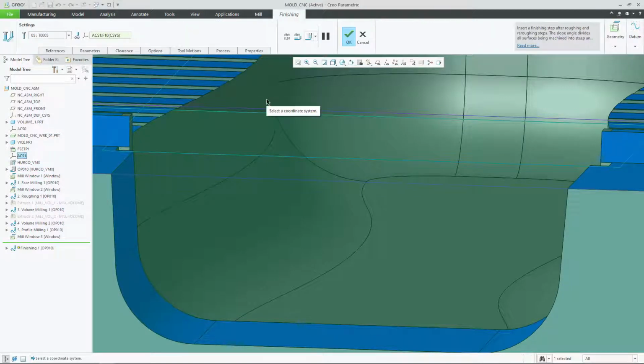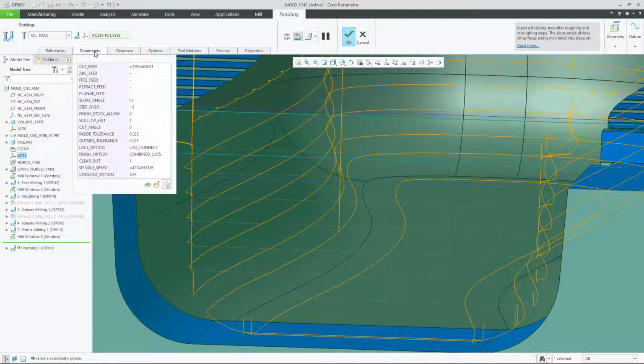And you very much end up working in this way of modify, run the simulation, assess whether you've had enough of an effect, and if you haven't, go back in and modify again. So it's an iterative kind of process. So show the toolpath, and I think this will be the last time that I modify this. So into parameters, maybe reduce the height down maybe to 0.8.